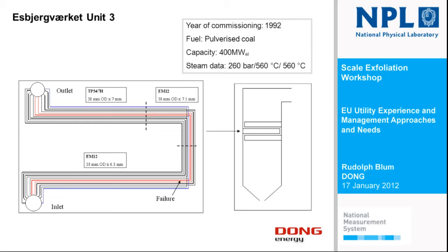When we made this hydraulic testing, we filled up the boiler from the bottom, came up to the outlet superheater, and filled it up this way, up to the outlet box. When it was filled completely and the air taken out, the test was conducted, and we drained the boiler the opposite way, and then put it into service. Very few hours after being in service, we had the first failures.